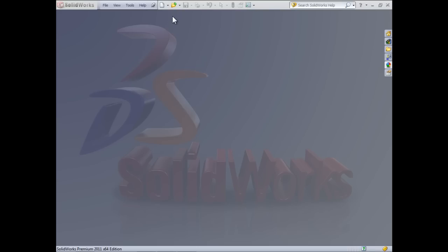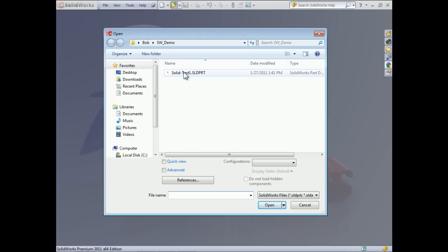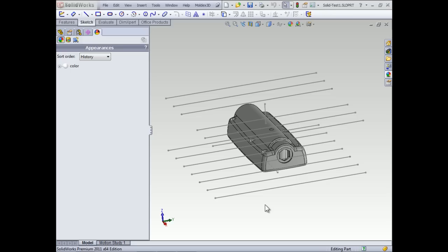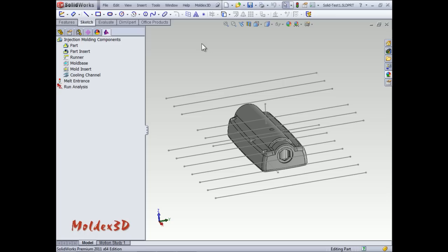After activating SolidWorks, click on File and Open to select an assembly file, then click Open to import the model. Users can select and import any solid part file. After importing the model, please click the Moldex3D tab, which will show on the top part of the menu bar if we have installed Moldex3D eDesignSYNC, to start the pre-processing for the CAD model. All of our moves will be completed under the Moldex3D tab within the SolidWorks environment.